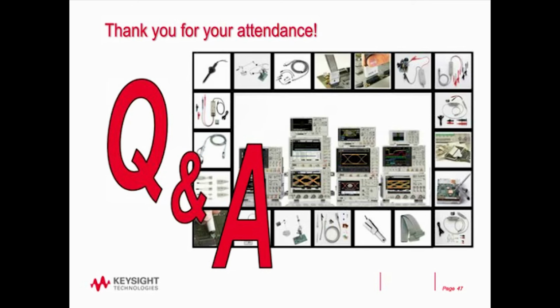We also have a probe we introduced about a year ago that is made automatically for this. It has a sense resistor technology, and you can embed these connectors on your board and then plug in the probe. It's got a make-before-break technology such that you don't have to break the line.